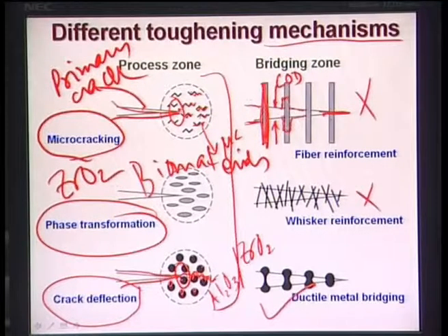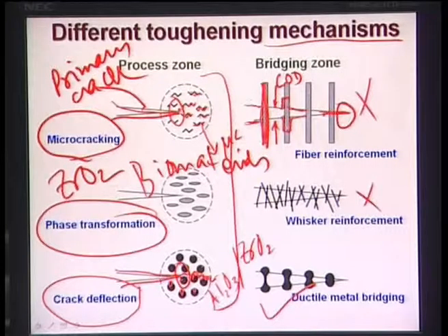And how does this fracture take place? At the crack tip, the fiber matrix interface is brittle, and if there are some cracks on the fibers, then cracks will go to the other side of the fibers, delaminate the fiber matrix interface, and then propagate further. Each time a crack interacts with a fiber, the crack opening displacement significantly reduces, until it is completely closed, meaning cracks will not propagate any further, and that is the point where the major toughening is achieved.